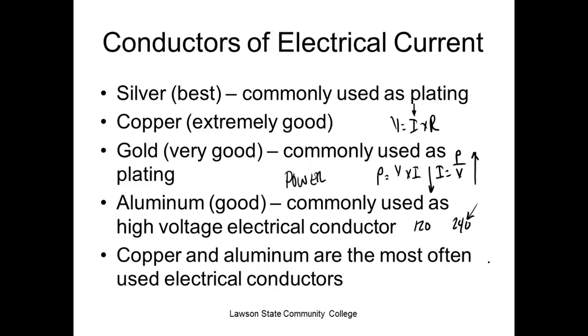So they send it at 200,000 or 300,000 volts. Now instead of using copper, they can use aluminum, and they can use a smaller gauge wire. That's the purpose. That's the only advantage high voltage has over low voltage, that we can run it with smaller gauge wires. Everybody understand that? So all your high wattage devices are on 240.